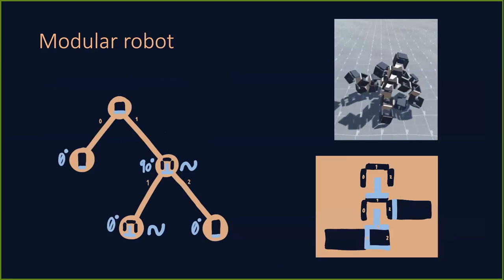Our robots were encoded with a direct encoding, which you can see illustrated here on this slide. Each robot is represented by a tree structure that you can see on the left here. Each node in this tree contains information about a module, what type of module it is, and also what is connected to this module. And for the actuators, also the rotation of the module and the controller for the module, and also the springiness of this actuator is recorded in the node.